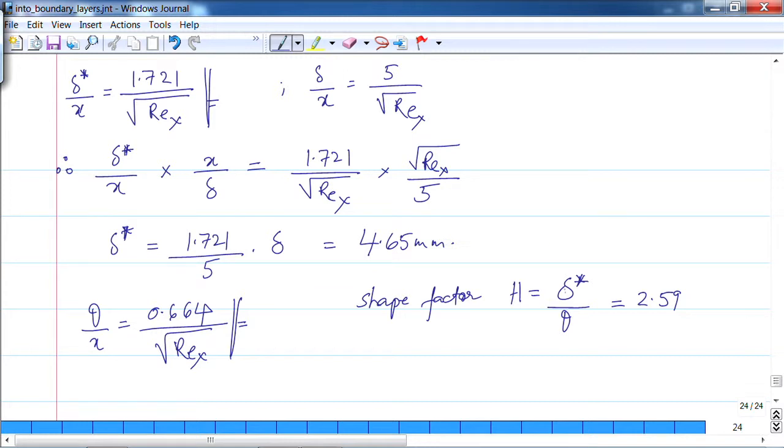Anyway, whether you use this formula or this one, what you get is essentially this. So theta is 1.79 millimeters. This is what I get. Now, this first case was for air, so the fluid was air, and you need to do the same thing for the second case. So go ahead and do that.